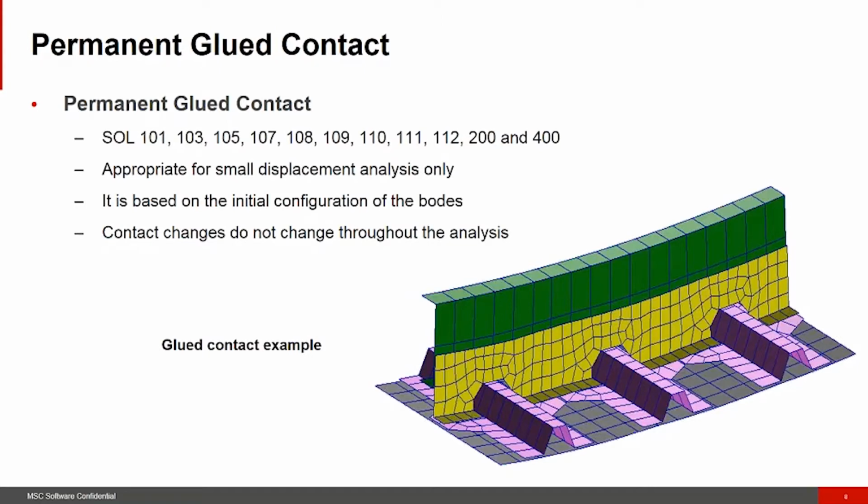This is the best option, an ideal option, when you have to model multiple parts in a structure and quickly assemble the components together that have similar meshes and connect them to create a full assembly. So there is no need to have the same size elements. There is no need to have congruent mesh, and you can contact several bodies together.